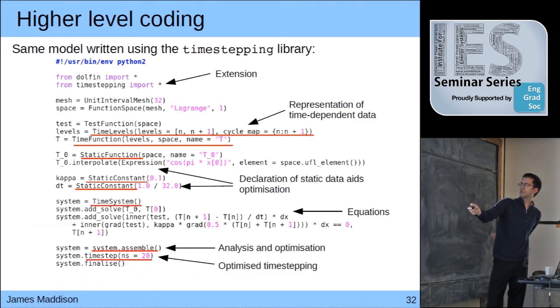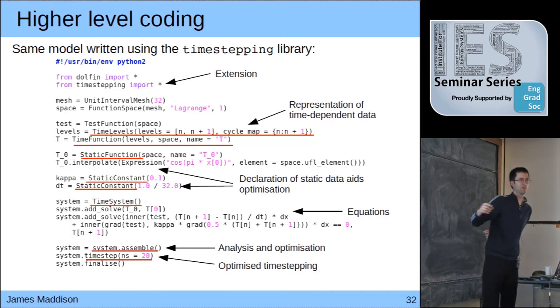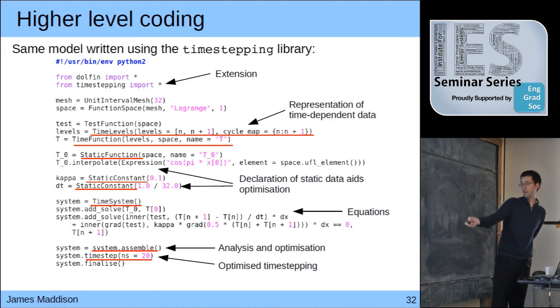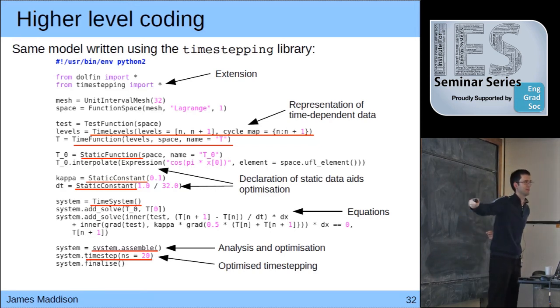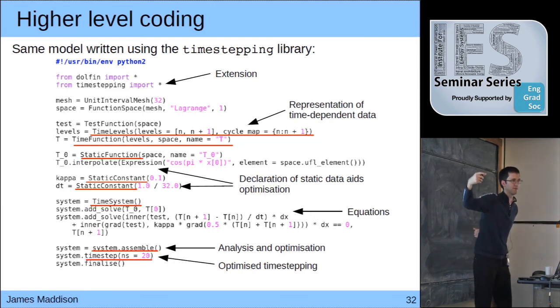Here we're using the FEniCS system, and then we're using the extensions from this library, and the only differences that really turn up are that we have a way of writing down the integral of a test function times temperature at the future time minus temperature at the present time, and then temperature at the past time plus temperature at the future time. It turns up in here. We just added a way of writing down subscript n plus 1 and subscript n, and then the tool takes this code and works out that tons of stuff in here can be computed once and reused for multiple time steps. So again, we just have a very, very high-level expressive representation of a time-dependent code, and it's optimizing at the equation level and caching stuff for you in this problem.